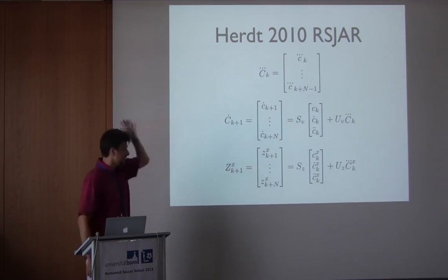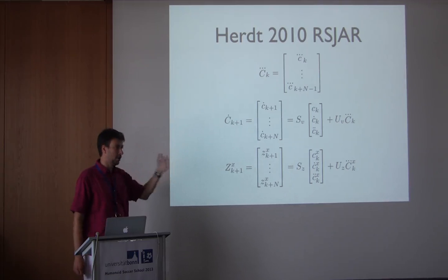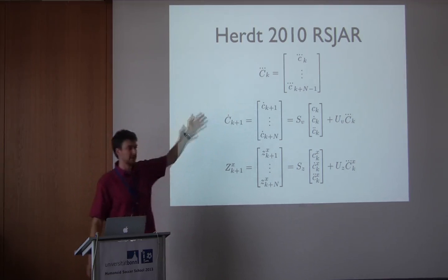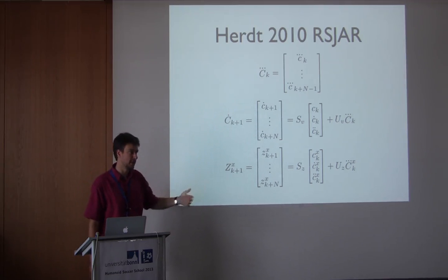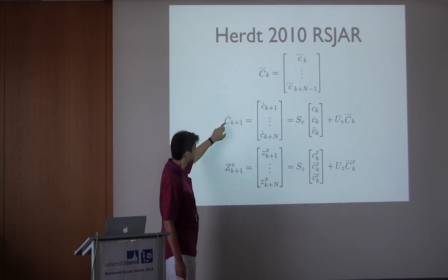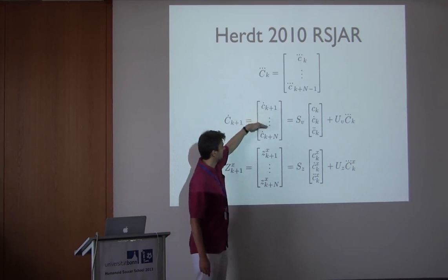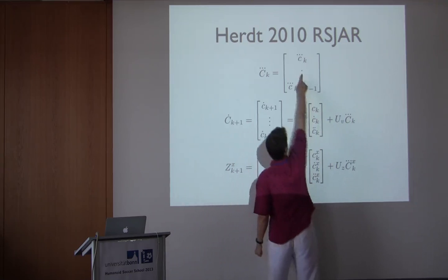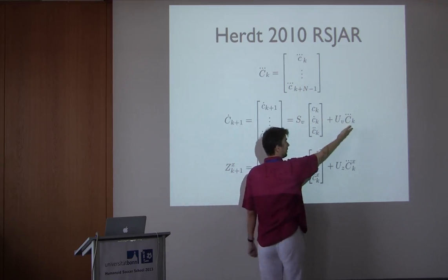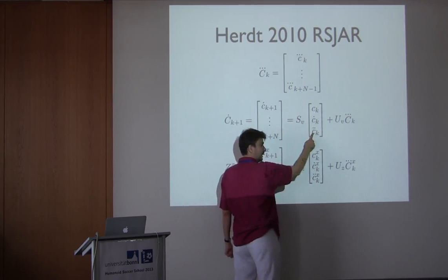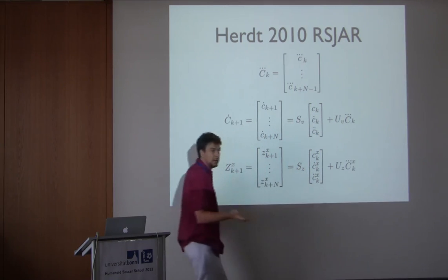And depending on this, of course, you can integrate your dynamics. Here you have the third derivative, you can integrate the second derivative, you can integrate the first derivative, and then you have the motion position. So here, if you say that you have the speed of the center of mass for the next n sampling periods, they will depend on this vector here of jerk, with some matrix here, and it will depend on the initial state with some matrix here, linear.